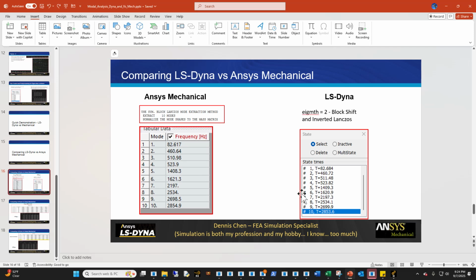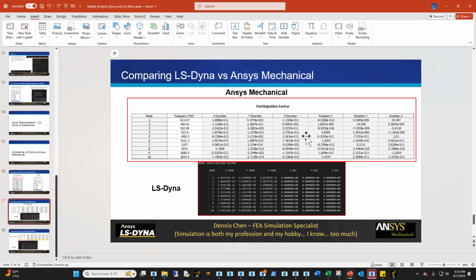Over here, I'm using an 8-noded brick with ELFORM 2. Over here, I'm using a 20-noded brick with enhanced strain formulations, which I believe is a Workbench default. So that's something I can investigate and make sure I understand. And that also might be the reason you see I have zero rotational degree of freedom over here, even though I have more inside the Mechanical side. This is the only discrepancy that I haven't been able to resolve, so something I'll follow up on myself in the future as well.